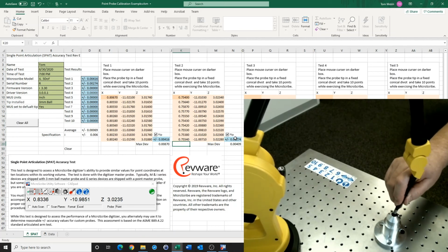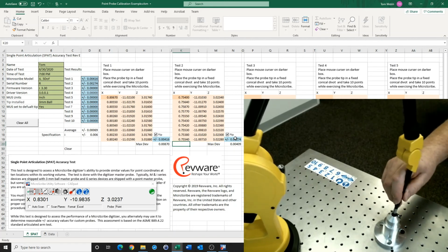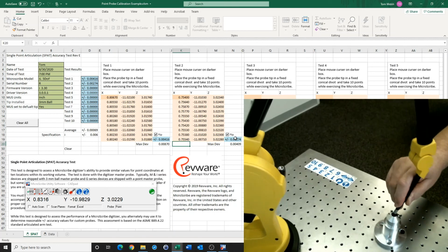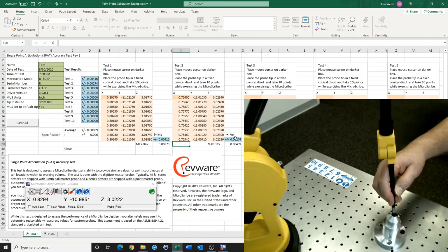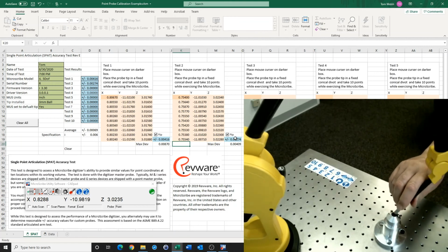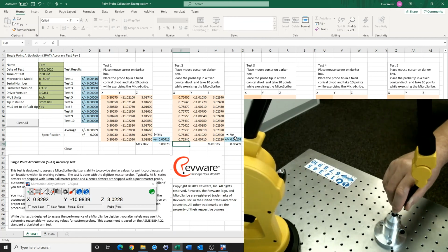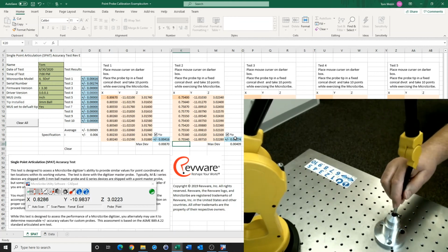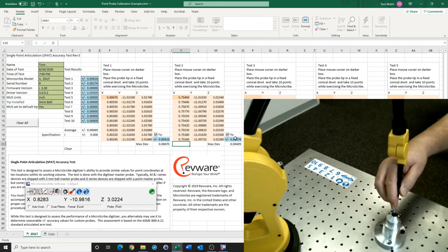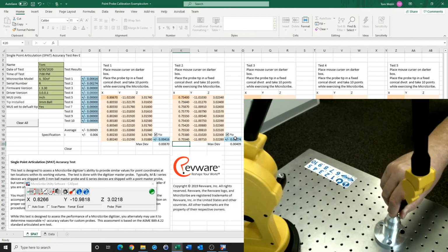But once you get a spot, move the stylus around on that point a few times to get comfortable with it being in that one spot, and then commence with your data collection. If it should slip at all, you are going to have to start over. But with a little practice, it's actually not hard at all to calibrate a point probe.